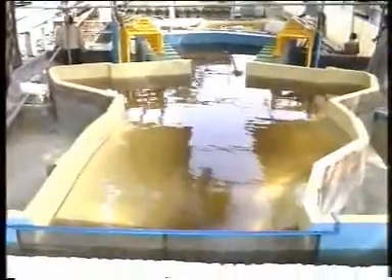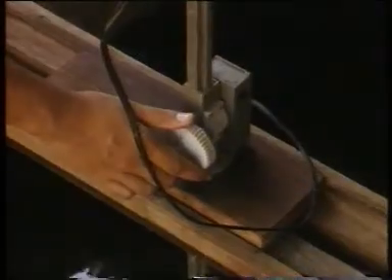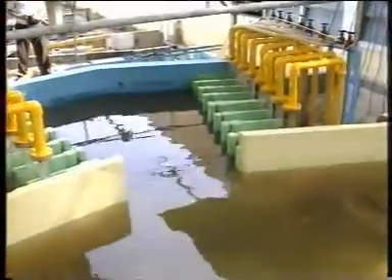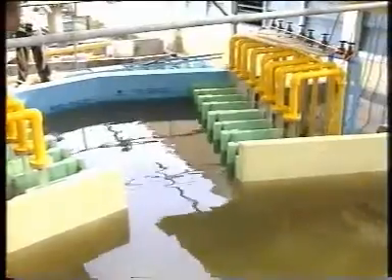The pumps are individually operated by maintaining the water level at FRL, and measuring the discharge over the calibrated 90-degree V notch. Similarly, the water level is lowered to minimum water level and the experiments were repeated.